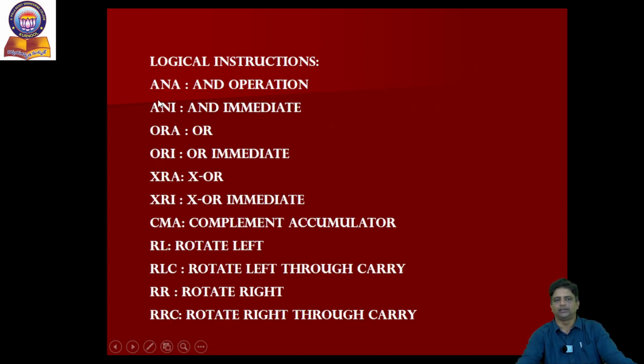Some other instructions are listed under the logical category: AND, OR, XOR operations. In continuation, with the shift and rotate operations, we will have RAL, rotate left, RLC, rotate left through carry, RAR, rotate right, and RRC, rotate right through carry. Another interesting instruction here is CMA, complement the content of the accumulator.